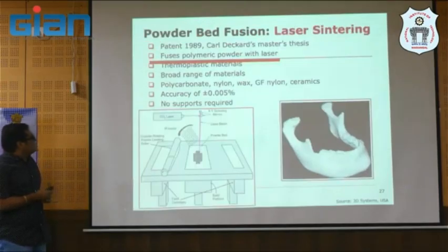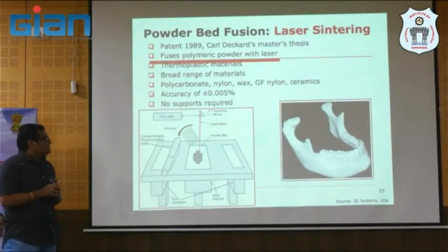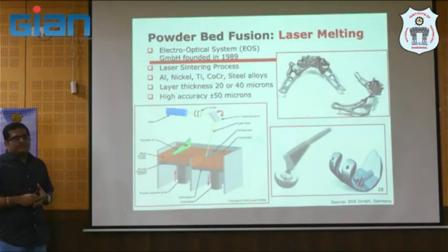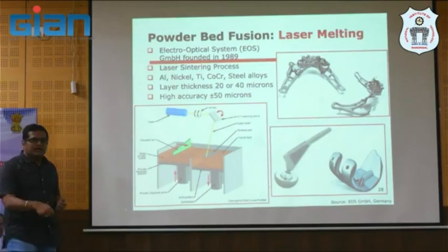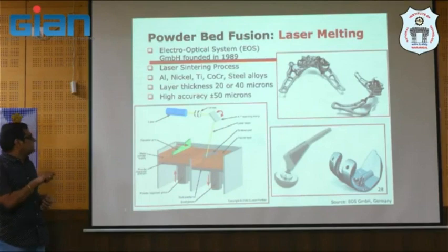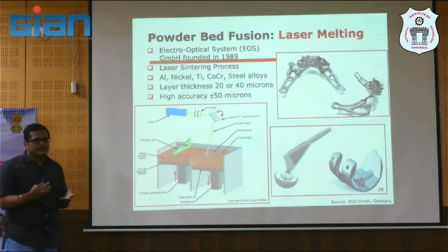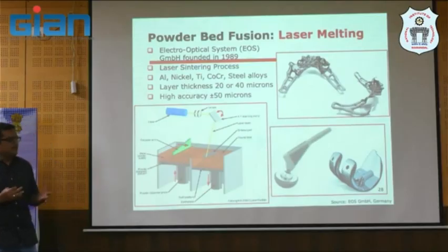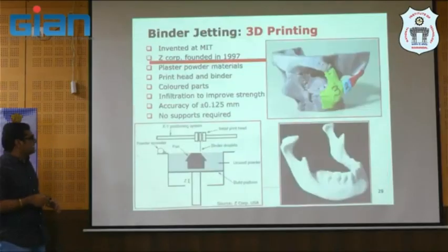Anyway, you have powder bed fusion with polymer, or even with metal. You may be interested in metal because you are going to print some implant, maybe a dental implant, or a knee, or knee braces, or a femoral joint. So you may be interested in powder bed, and that too with titanium 6-4, maybe cobalt chrome or 316L, right? Then you can process it very well here.